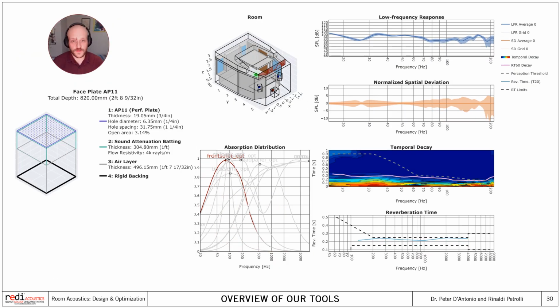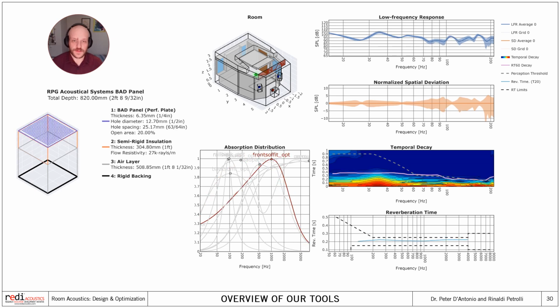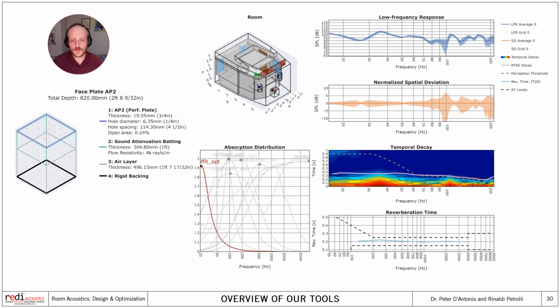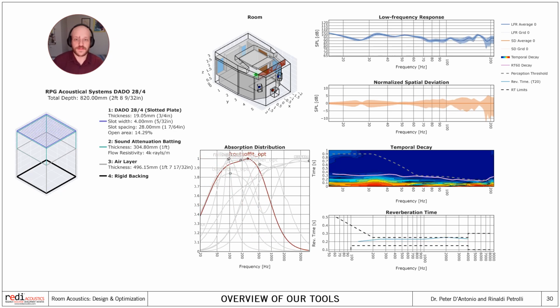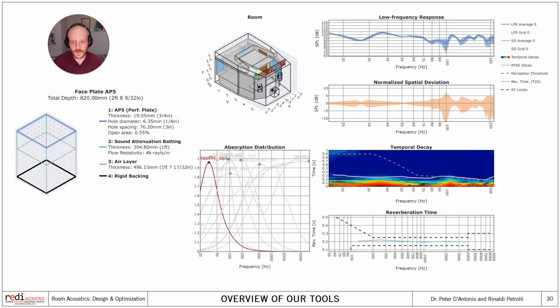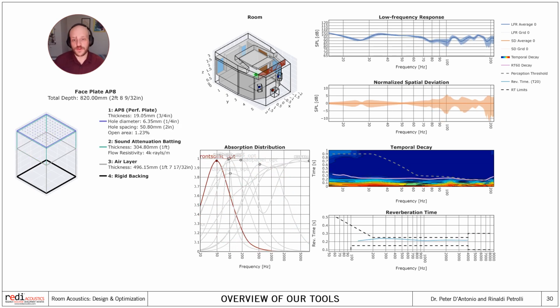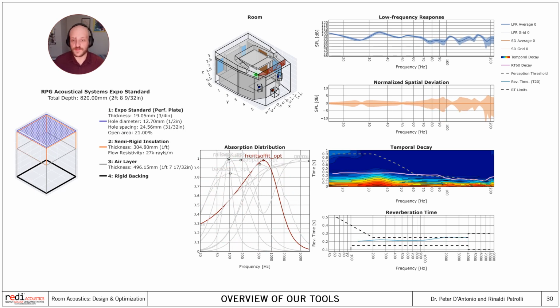Building on the same principles that TORA uses, we developed an auxiliary tool called the Treatment Sweeper. This tool allows us to take a very focused look at the frequency response by applying different absorption distributions to all treatments. Essentially, we take a single treatment and evaluate all the possible configurations it can have in terms of absorption.